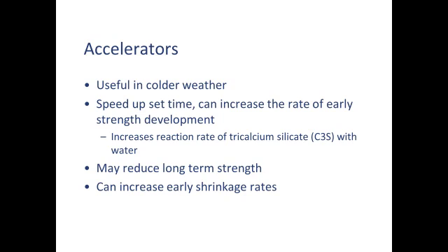And that's why if you've ever seen the strength curve, you get most of your strength in the first week. You get about half your concrete strength in the first week, and then it tapers off, and you gain most of the rest of the strength in the last 3 weeks after the first week. And that's an indication of where your early strength has a bigger effect on the rate of strength gain. And when we're in production, everything is about early strength gain.